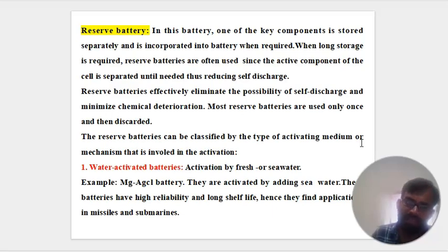When long storage is required, reserve batteries are often used since the active components of the cell are separated till needed, thus reducing self-discharge. Reserve batteries effectively eliminate the possibility of self-discharge and minimize chemical deterioration. Most reserve batteries are used only once and then discarded. The reserve batteries can be classified by the type of activating medium or mechanism that is involved in the activation.